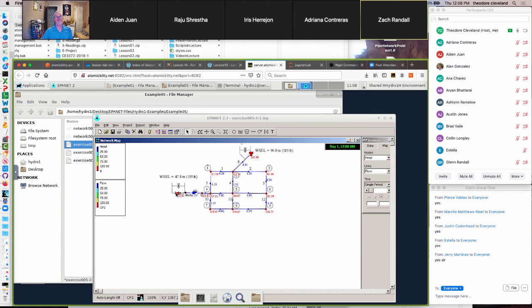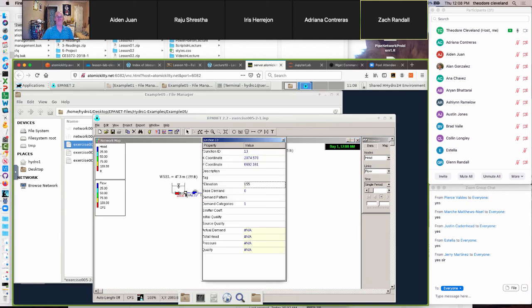So this is drawing water at 155 feet into a node of elevation 155. That doesn't make sense. The water doesn't really have to be higher than the node, but normally you would draw water from a lower elevation in the reservoir. I'll leave it be, it should run.